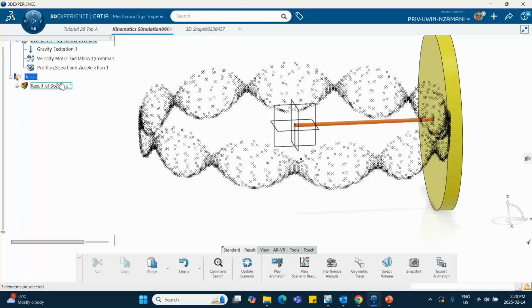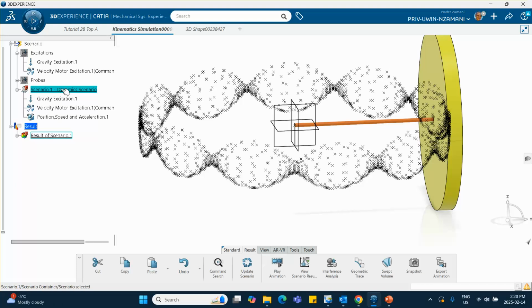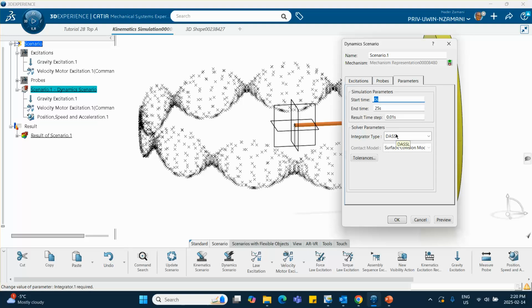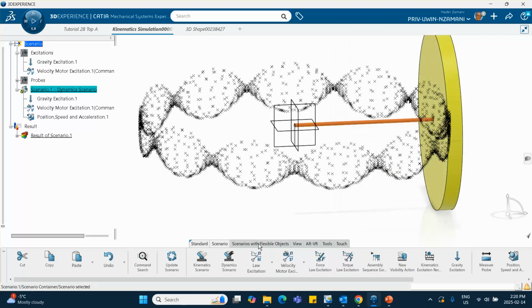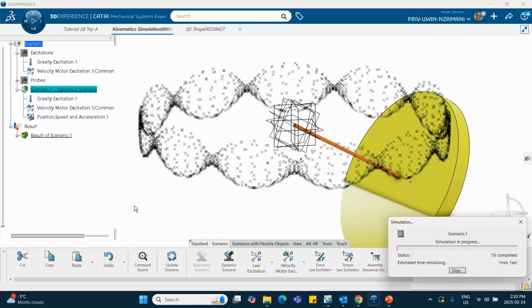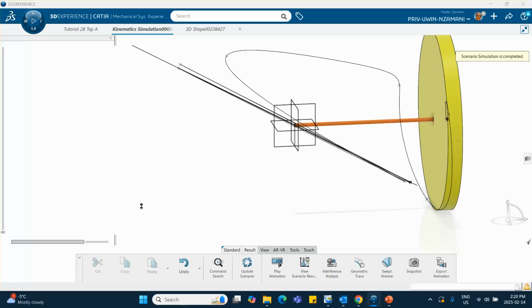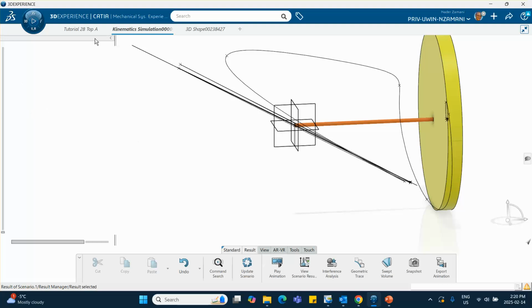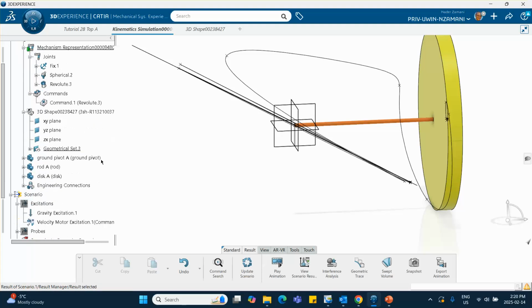Now, let's go ahead and change our integrator, from DASSL to symplectic Euler. Let's say we leave everything the same and run it. I may have to kill it at some point. It actually bombs out, but we can make it actually work. However, you have to change a few things.